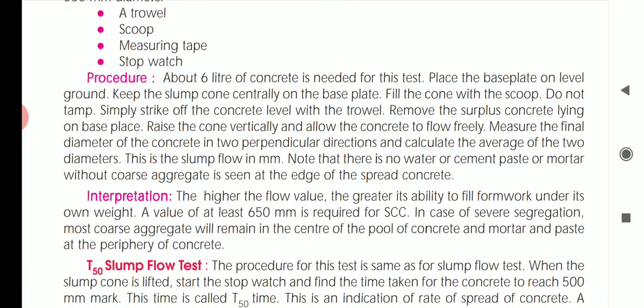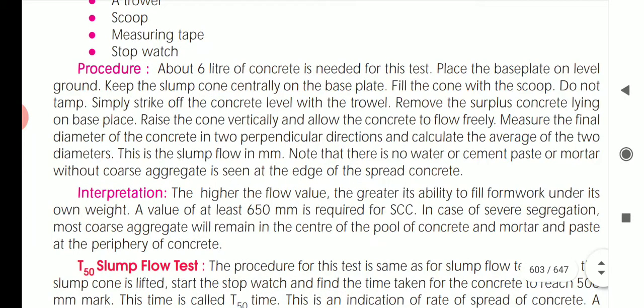Note that no water and cement paste or mortar without coarse aggregate is seen at the edge of the spread of the concrete. No concrete and water should remain at the surface. It should be mixed with the aggregate.